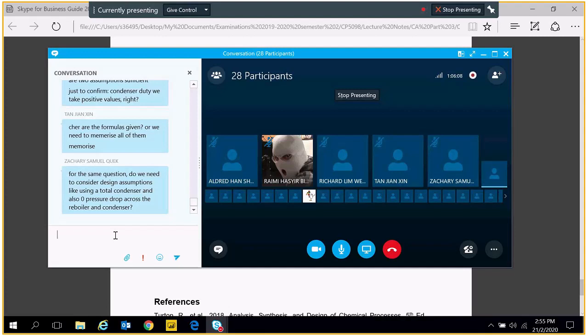The Darcy equation you have to memorize. I mentioned that you should not use a formula to calculate the Fanning friction factor. The reason is that if you got your calculation wrong, you don't get any mark. But if you use the Moody plot, and you did your Reynolds number correctly, you get 1 mark. Sometimes if you do your relative roughness correctly, you get another mark. But if you use a formula for turbulent flow and calculate the f, if you got it wrong, you don't get any mark.